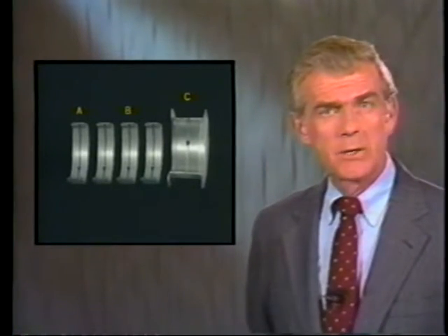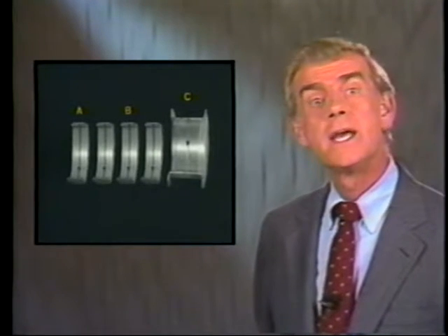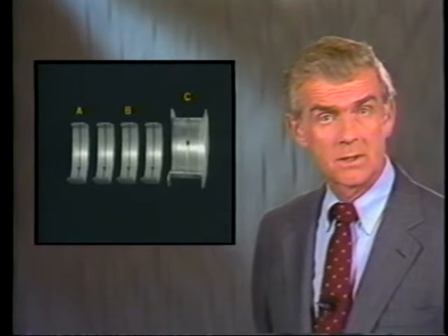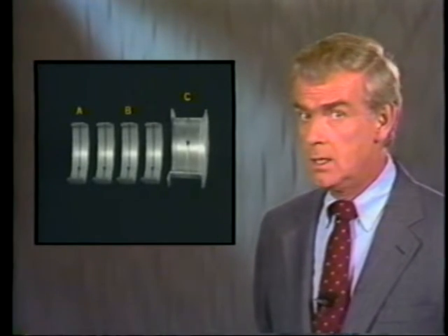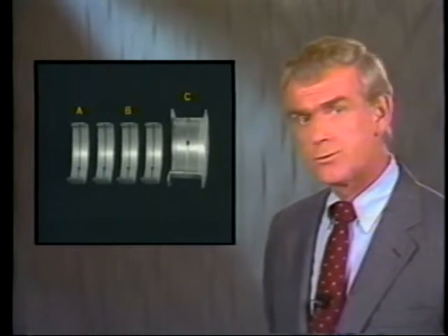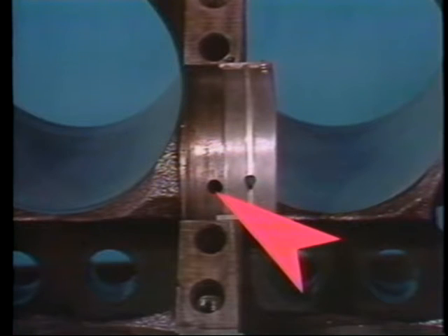While the crankshaft bearings support the crankshaft, bearing C also keeps it from moving end to end. Technician A's statement, therefore, is true. Technician B's statement, however, is false. The bearings shown have a hole drilled in the center. This hole is where pressurized oil is fed to the crankshaft bearings from the oil galleries in the engine block.